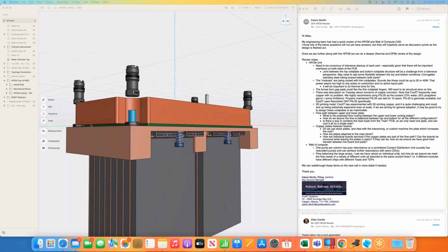I was thinking like a rubber washer where you've got some compliance in the vertical direction, so as you bolt the two together, you get compression there. Yeah, the difficulty is, when you have a gasket like that, usually there's a specific range you're trying to hit with compression, and you want it to stay within that, versus we're asking for compliance in that vertical direction.